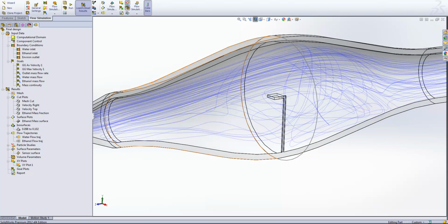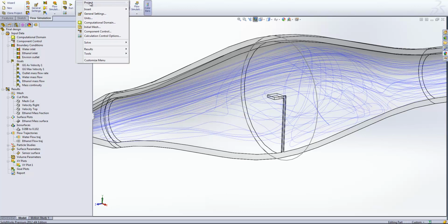That's very, very easy to do if you've got SolidWorks Simulation or SolidWorks Premium, so the FEA analysis tools that SolidWorks gives. If we come up to the Flow Simulation tab, you'll see that we have the option to export results to simulation, and then it's simply a case of selecting from the simulation menu, include flow results, and all of our flow characteristics will be used in that FEA analysis.